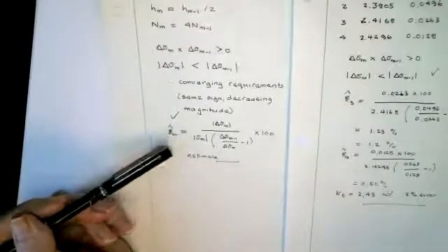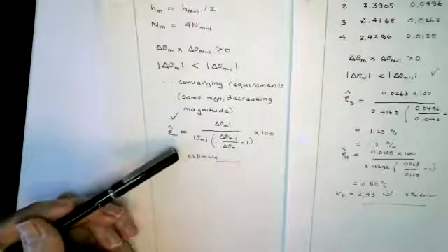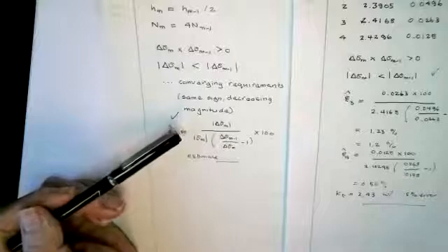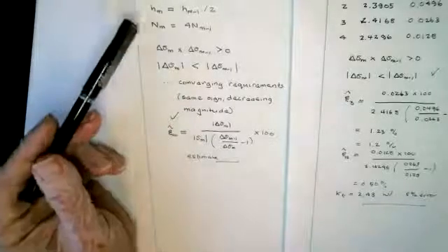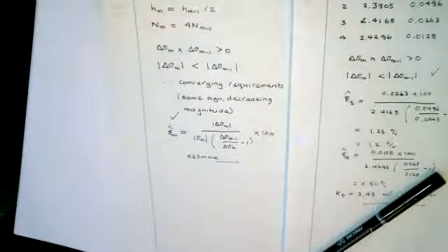We can also get an estimate of the convergence rate here, which is interesting to see how it compares with what's called the asymptotic rates. But this is the key thing here. And in order to do this, you have to have this mesh refinement. If you think about people who started using n plus 2n, 3n, 4n, what happens if you get to mesh 100n? So the next mesh is 101n. That's a 1% change in your mesh. That's not checking for convergence. So that scheme was computationally convenient for the people who practiced it, but basically seriously flawed and useless.